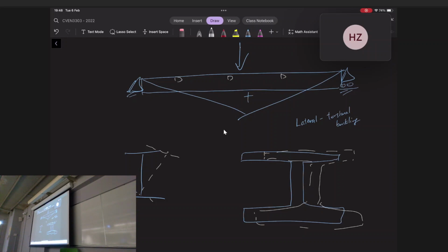extra beams that were framing into the top like that? Because in real life, you'll have beams that are crisscrossing, right, when you're holding up a floor. So in this case, let's say I had a beam that was framing in like that. Imagine this sticking on the board again, I have beams that are framing in at particular discrete spacings.